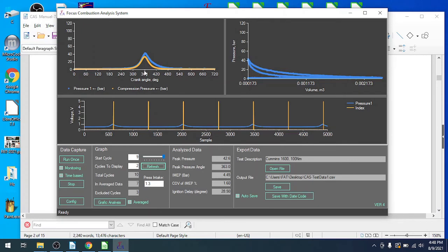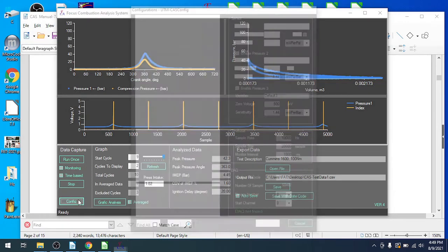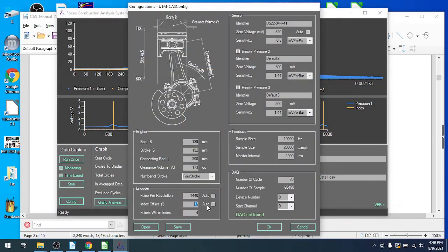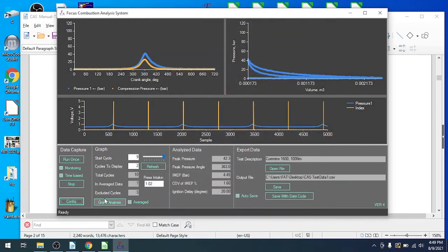Some of the other things we could do would be to say, well, let me change the intake pressure. In this case, I probably wasn't running 1.3 intake pressure. I was probably running just about 1, maybe 1.02, we'll say, a very small number. Now you can see it's looking like it's deviating a little bit. We maybe want to move the trace over to the right some more. So we say maybe it's 18 degrees or something. Let's see how that looks.